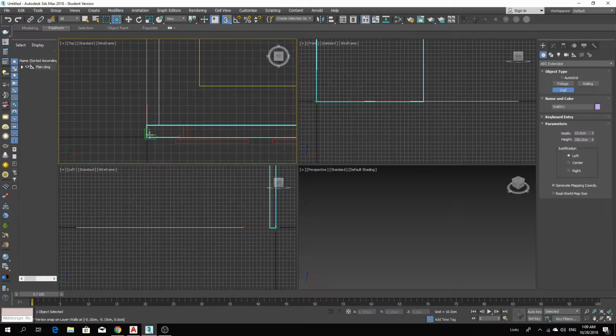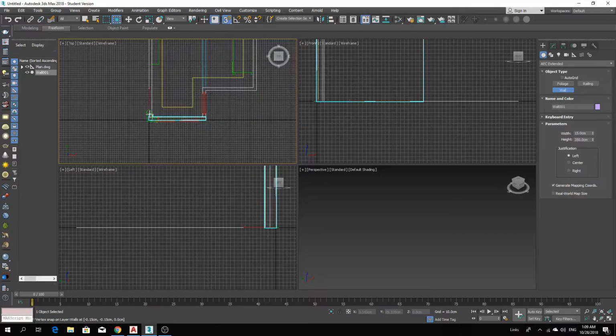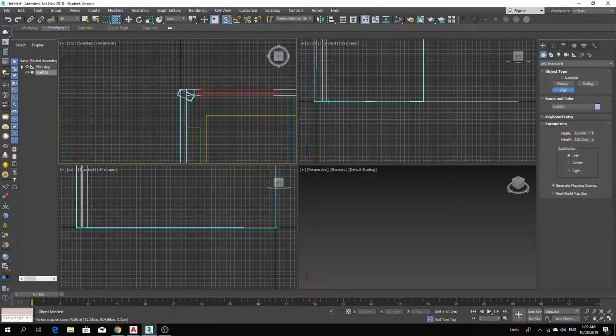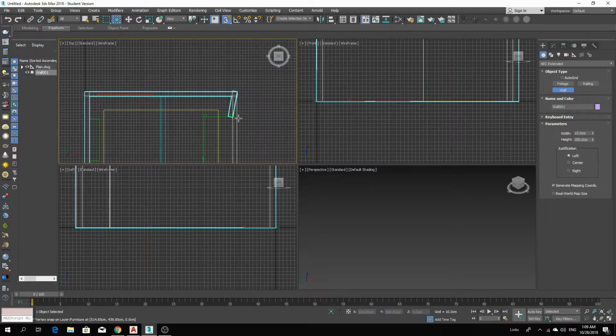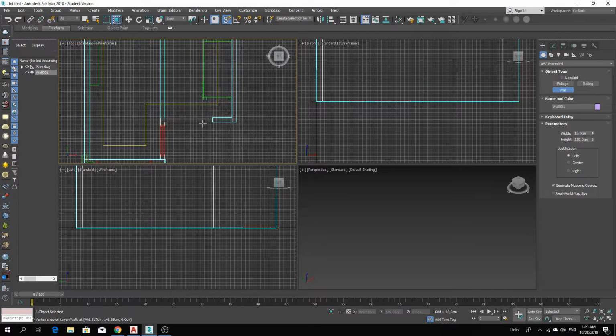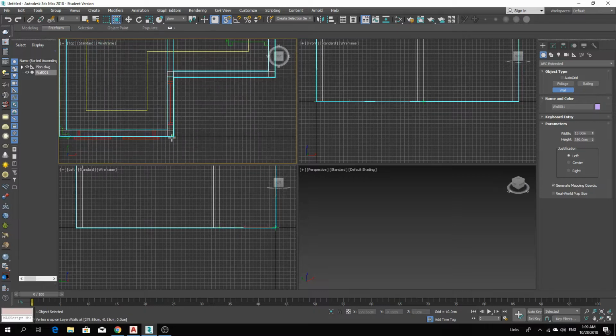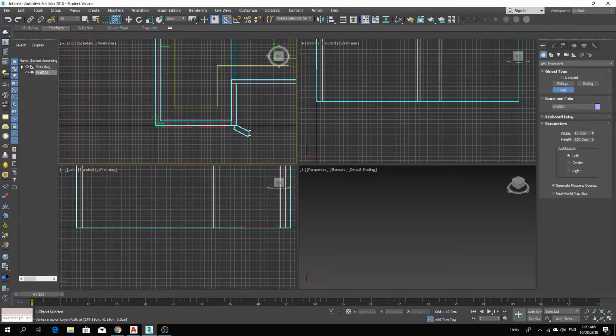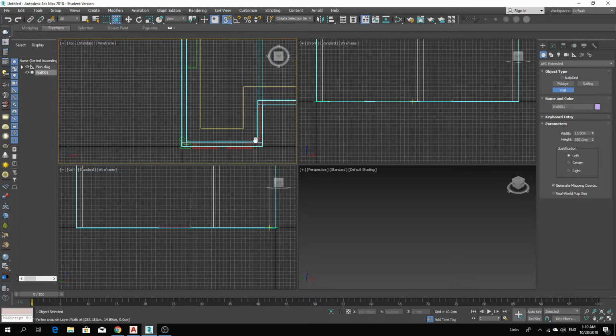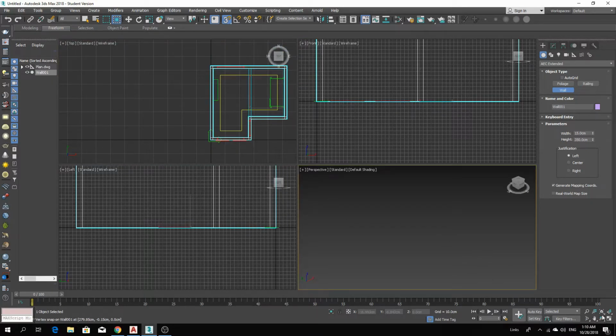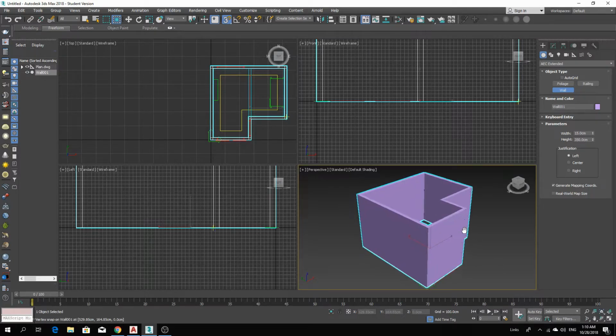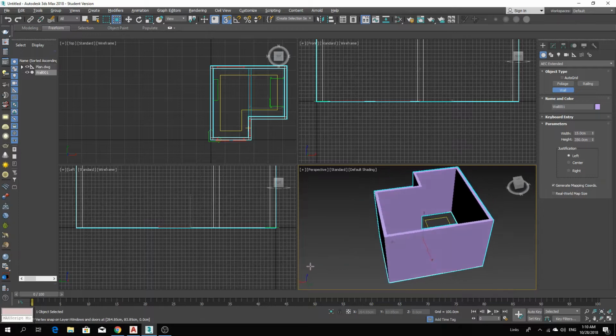So I'm gonna start my walls here, and I'm gonna click on every corner that I have. There, and I would say yes, weld point, or I would close the walls, and then right click on your mouse to exit the command of creating walls. I'm gonna click on zoom extend here so I can see my view. Okay, so this is what I have so far.